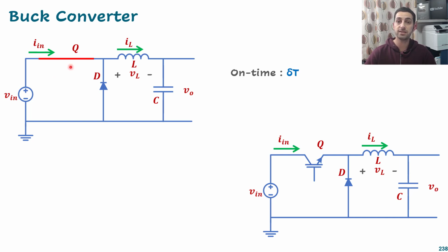Now let's understand how the other components in the circuit behave if that is shorted. So I think you will agree with me that the input voltage here will push some current. That current now will reach that point, and that's high voltage, okay, and will reach that point. What will happen to this diode? I think that diode will be reverse biased because the cathode has higher voltage than the anode. So that's why we agree that it's off.